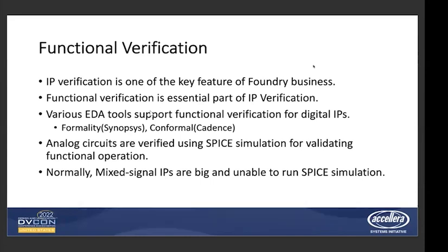Of course, SPICE can provide functional verification results of IPs. However, runtime of SPICE simulation increases exponentially following the design size. Especially large size mixed signal design IPs such as memory design are unable to run SPICE simulation due to the runtime issue.